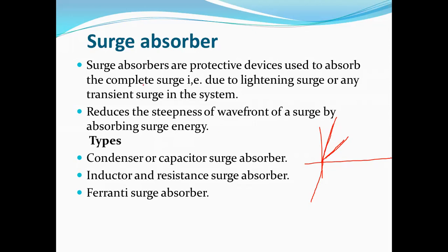So this surge absorber is reducing the stiffness of the wavefront, meaning that sudden increase in voltage gets reduced, because the surge absorber is absorbing that surge energy.